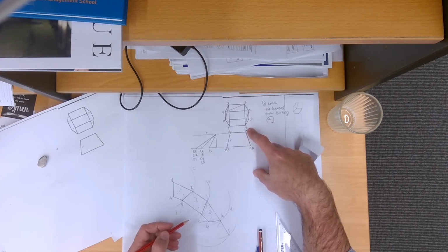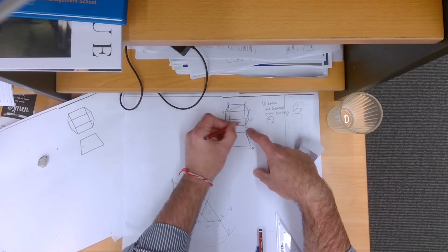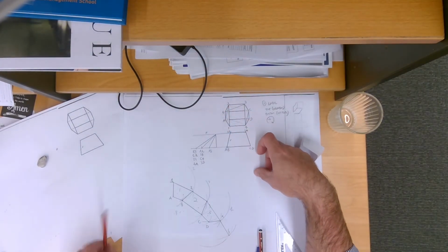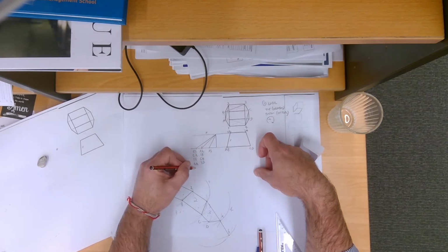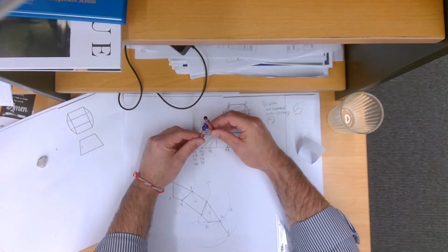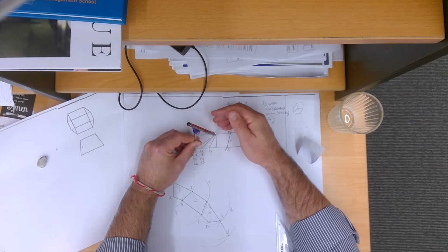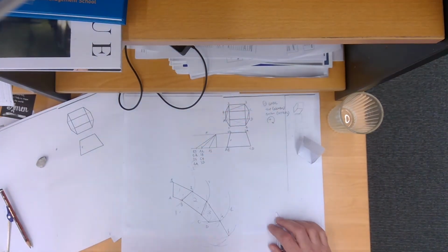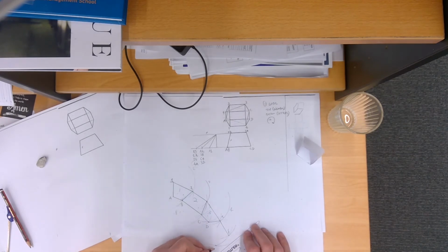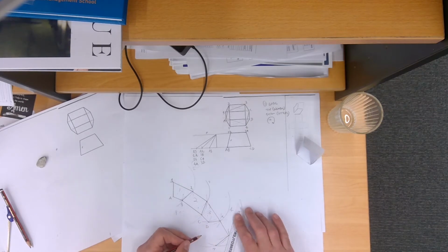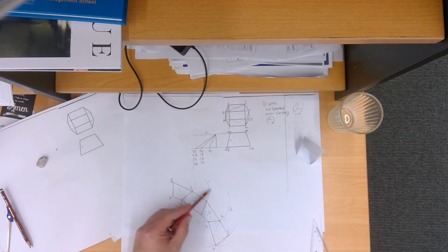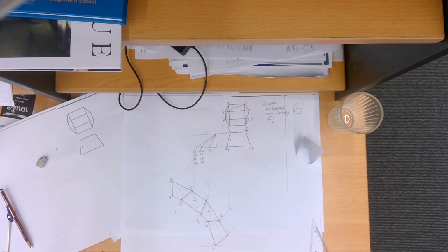And 4A is going to be the same as that one as well, because these two are equal, and these two are equal. So we know that our 4A is like our B3. Swing from 4. We find the point of intersection. It's back to our A. That's where our seam is. And we do that. So that's our shape. I am going to photocopy this and cut it out, and I'll show you what it looks like.